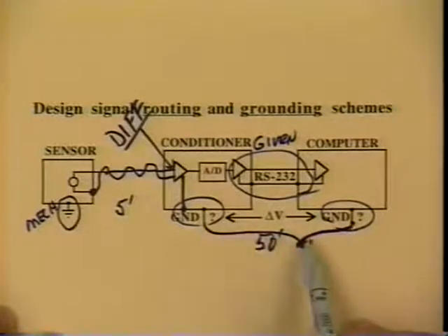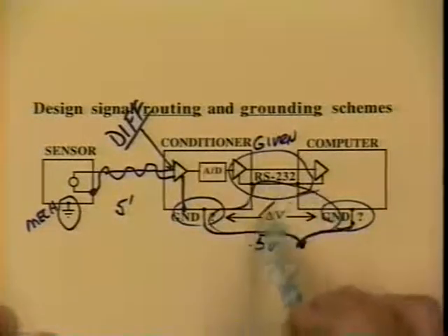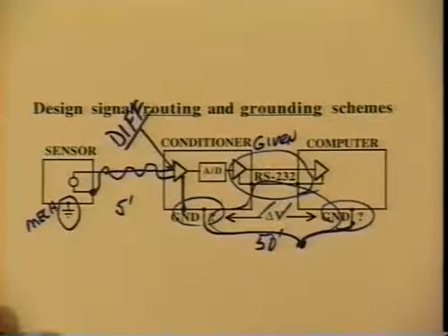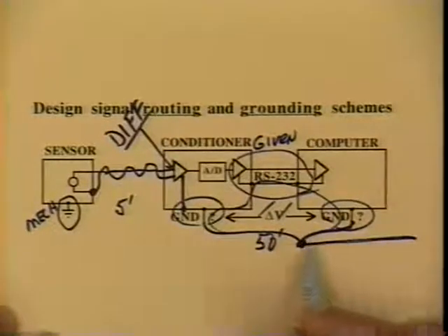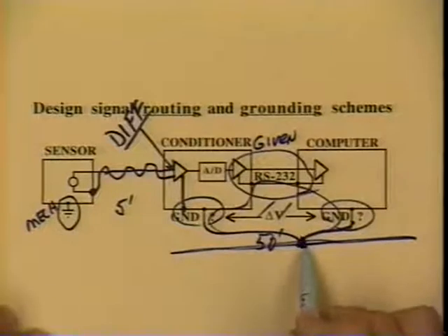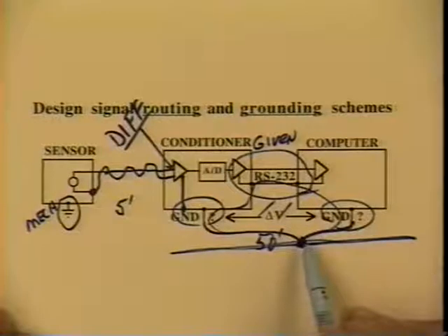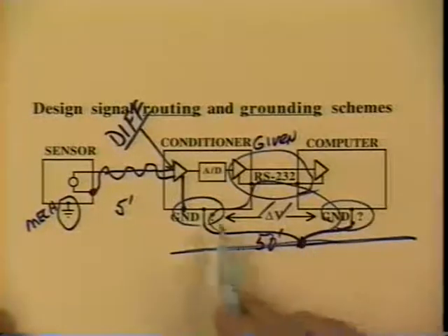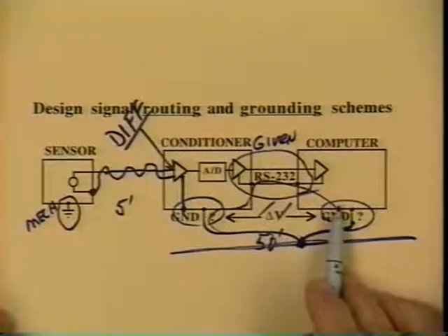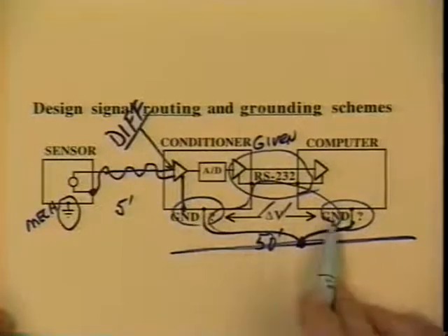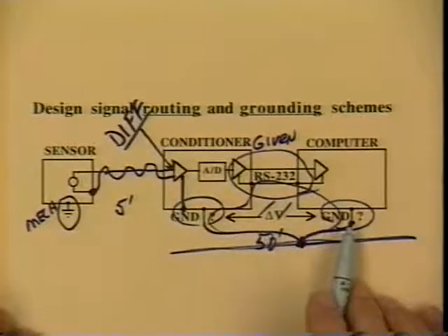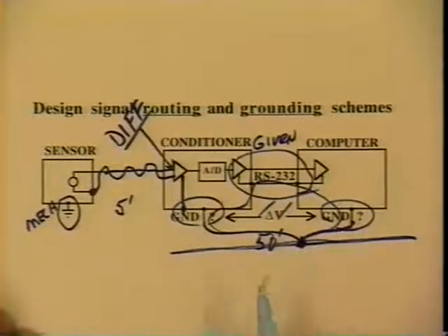And by using a single point safety ground, I still have a ground loop that is susceptible to magnetic noise, but by contacting the building structure at only one point, I don't pick up nearly so much conducted ground loop noise. Now, you can only use single-point safety grounding when the safety conductors are running relatively short distances, 20, 30 feet maybe. If these chassis were several hundred feet apart, of course, the common mode ground voltage would be a lot worse, and I couldn't fix that by attempting single-point grounding. It just wouldn't be an adequately safe thing to try.